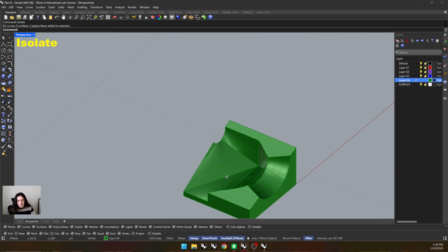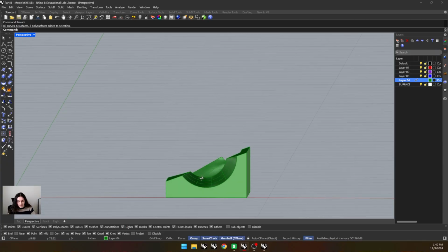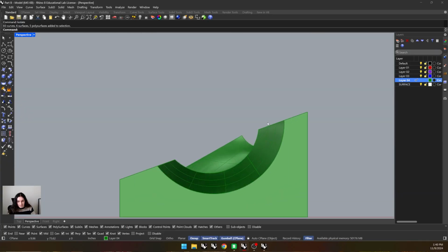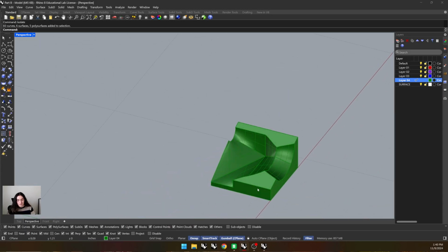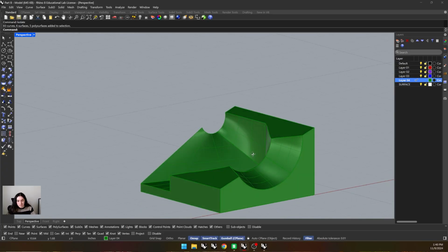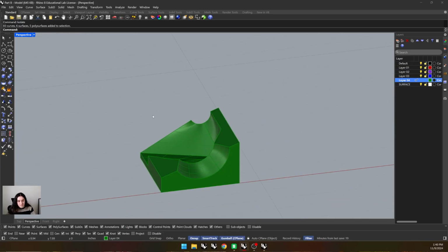is that the geometry doesn't have any overhangs. And what that means is, you can see a curve here, but if this curve were to continue up and over, I would have a cavity that would make it difficult to pull this print off of, or this negative off of the positive that I will cast into it. And so that's kind of what I'm looking for with these negatives.